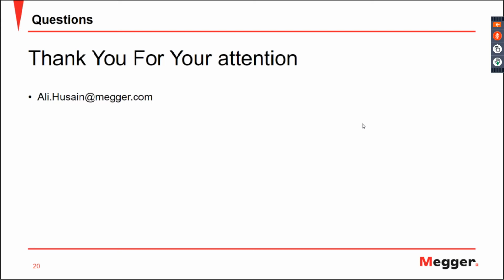Verifying this will not only give you indication that the relay is stable, but also when you do all the next tests, the pickup, the timing, the slope, even the harmonic tests, you will not get valid results. And getting the keyword here is a valid result. You might get them pass, but they are invalid results, meaning they are not done correctly until you have passed the stabilization test correctly. It is very, very important to do this.